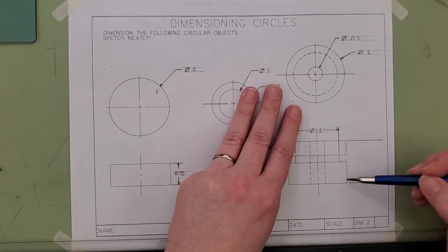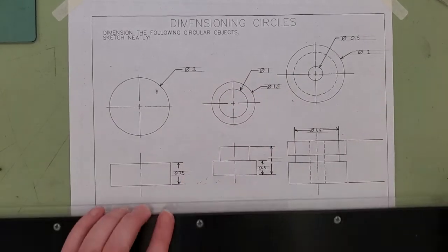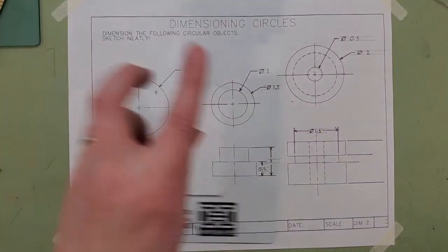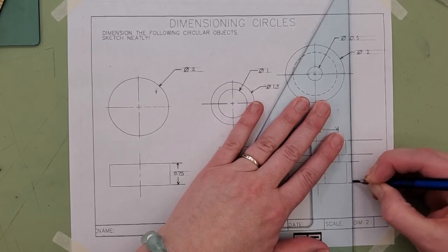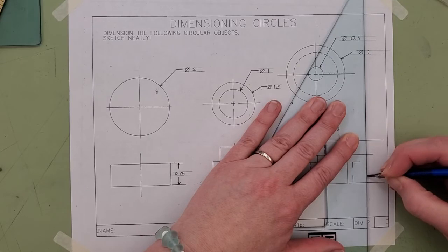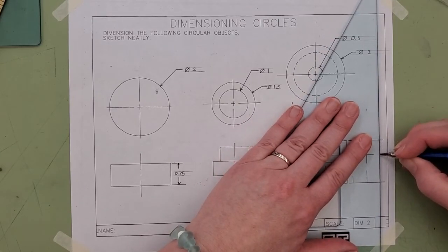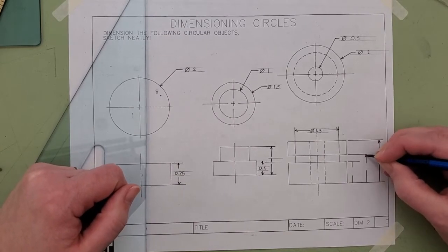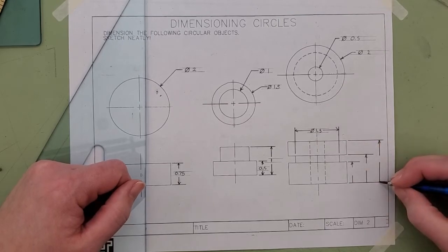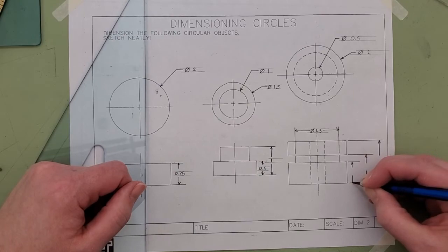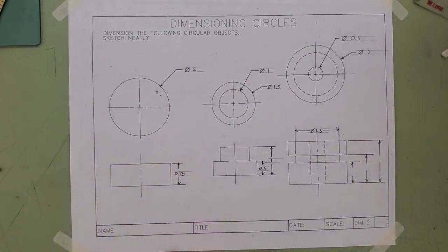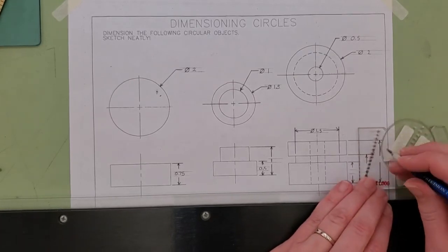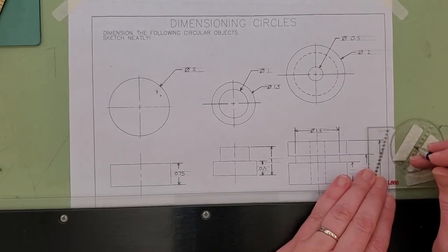And I like to do datum, so starting from the same point, but you can do this one and this one if you want. Whatever it is that you feel like is best for your style of dimensioning, go ahead and do that. Okay, the thing is, there's more than one way to dimension most of the drawings that we will be dimensioning. As long as you're sticking to the rules and keeping organized and nice and neat, then you should be okay.